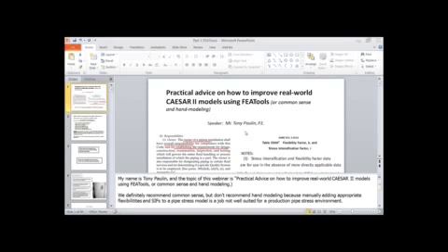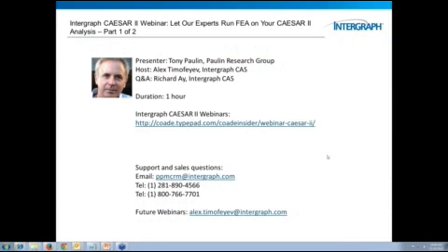Yes. I was in India presenting FEA tools, and I saw something that I wanted to share with the attendees. One of the clients had done a coker piping system. In that piping system, as you know, there are a lot of cycles and high temperature. They had tried to eliminate as many elbows as possible, so that when they're removing the coke, it won't get jammed up in the piping system. So they replaced the elbows with T's.